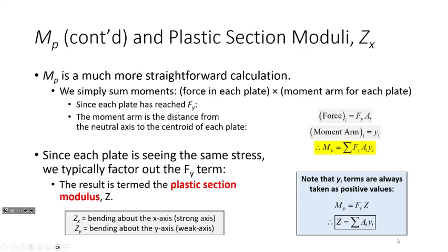So in concrete design, you're doing the same thing to determine maximum moment capacity, but in concrete, you're having to deal with two materials. So what you do in concrete is you assume that the steel fully yields, and for the concrete, to keep things simple, you assume that the concrete reaches a stress of 0.85 f'c, and in order to figure out the capacity, you're having to figure out the depth of the stress in the concrete such that the compression equals tension, and then you sum moments. So you have to look at it from a force equilibrium standpoint.